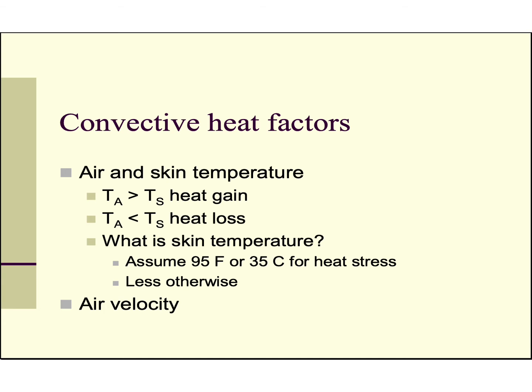The other factor we have to keep in mind is air velocity, which influences heat transfer by stripping away the blanket of air that surrounds the body that has been influenced by the body heat. So if the air is cold, the body will warm up a thin layer of air near the surface, and moving air takes away that warm blanket. So higher air velocity, at least to a certain extent, increases convective heat transfer, whether it's a gain or a loss.